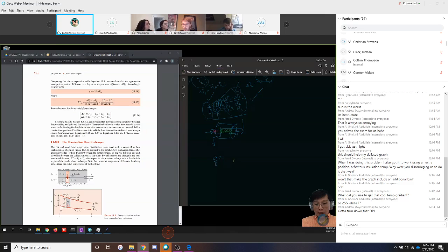So we had some sort of overall heat transfer coefficient. This is your U. And the value of U is what? You might remember for water to water, that's about 1,000. And for water to steam, that's about 3,000. On Monday, I'd love to talk some more about this.